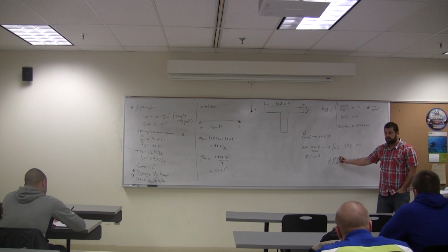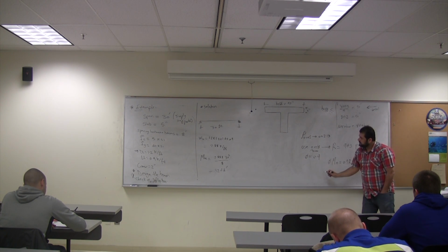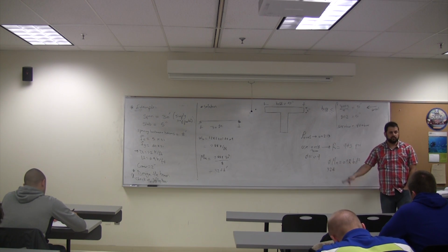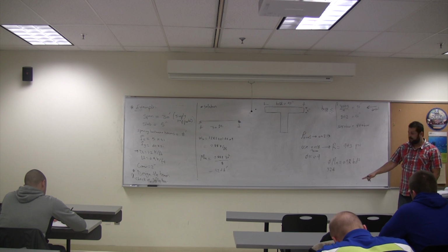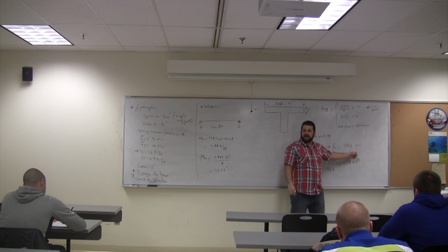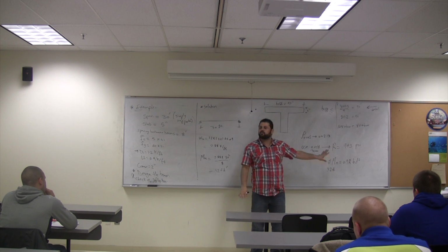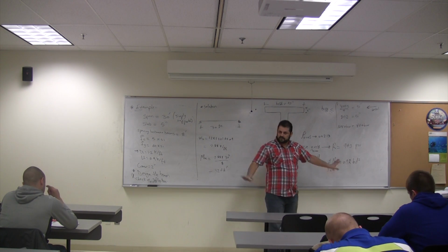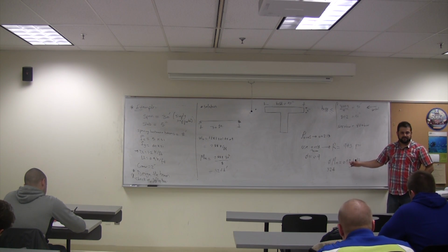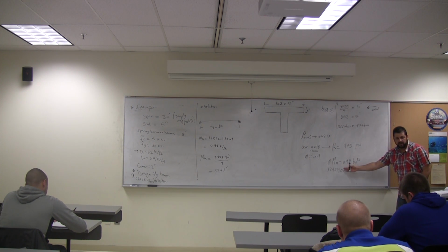Now Pmn here, from structural analysis, you make an ultimate equal to this: 3, 2, 4. Pause with me for a second. This is kip-foot. Everything in R and psi is in pound-inch. So right away you multiply by 12,000. This is the classical mistake in applying this equation. 12,000 to change it to inch-pound.